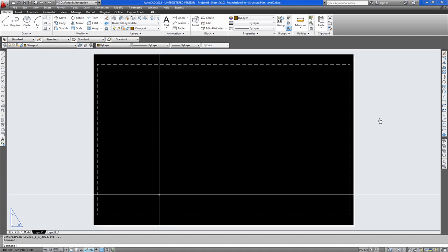You double click out of your drawing sheet, and now you go File, Plot, Extents. Now as you can see you have a small preview of the print here. Obviously you have a red line, so this is identifying a problem here, and if you previewed it you would see a problem, or you wouldn't see your model. It's because you need to center the plot. As you can see now, the shaded area is your plot within this square.